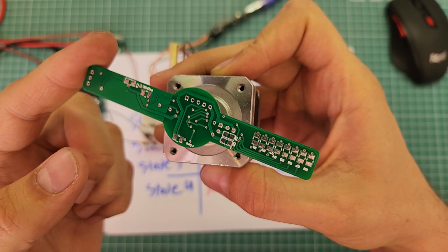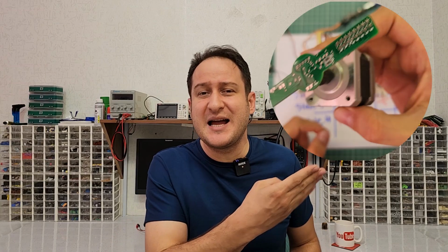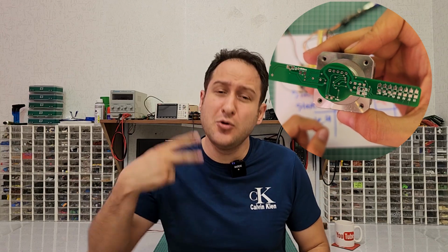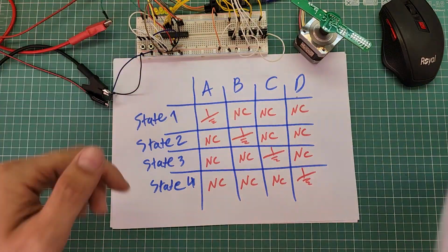The result is not what we expected. The motor may vibrate like this, and this is normal. It is happening because of heterogeneity between two PWM pulses on neighboring windings. I know you thought that this was the second problem I already mentioned, but no, this vibration can be simply fixed by using 4 capacitors on transistor outputs. Actually, these capacitors are converting PWM pulses into analog voltages.